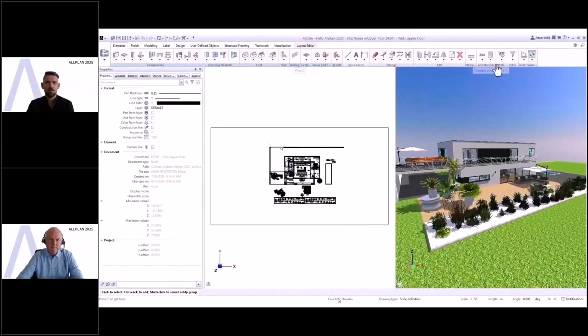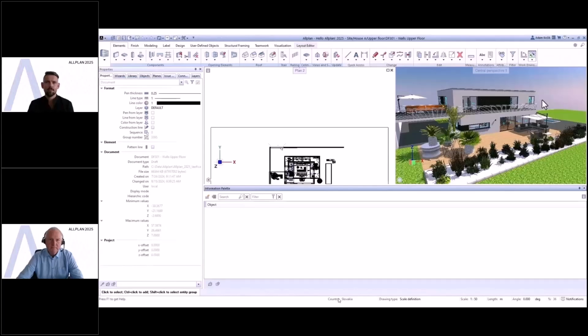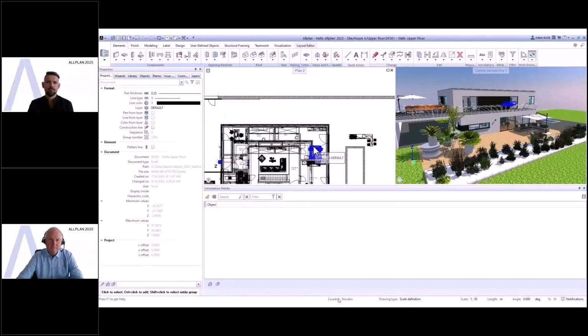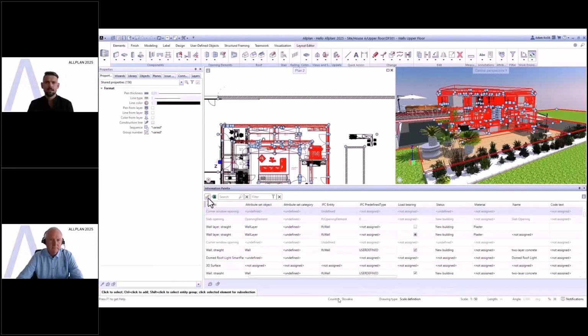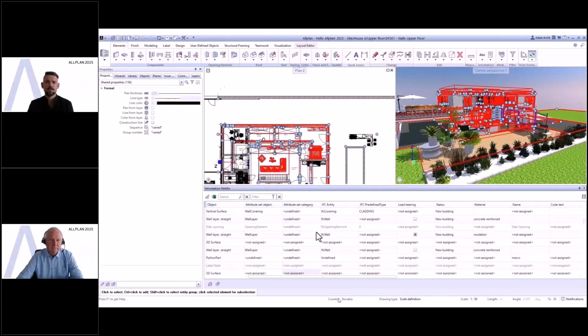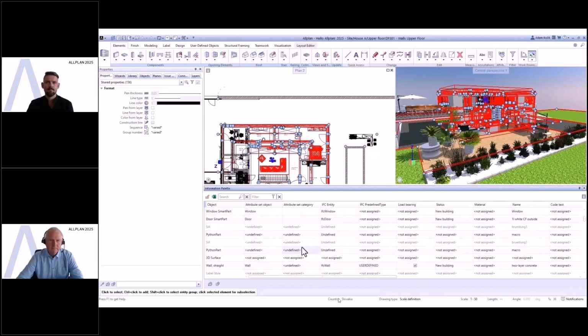First step is to open the Information Palette normally as any other palette. The Information Palette is opened and docked horizontally by default. Then you can select as much elements as you wish and hit Fill Information Palette from Selection button, and all selected elements are immediately populated into the table. Rows represent elements, while columns represent attributes associated with these elements.